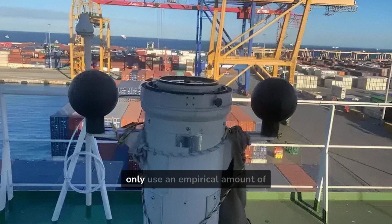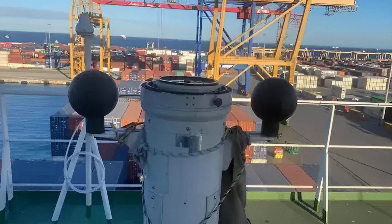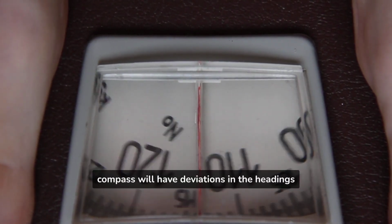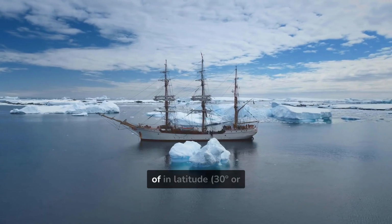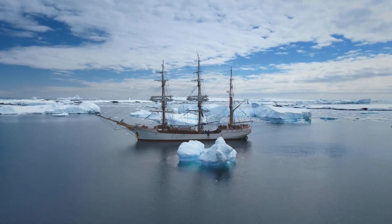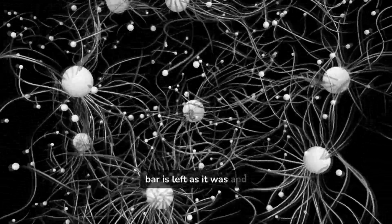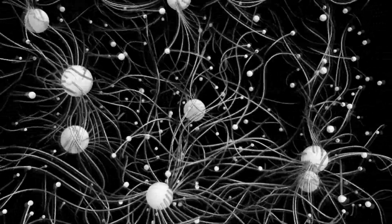The Flinders bar is installed when the vessel was built and the adjuster has nothing to do in this matter. Only use an empirical amount of Flinders bar, 30 centimeters. If the length is not appropriate, the compass will have deviations in the EW headings when the vessel changes a lot in latitude, 30 degrees or more. So, the Flinders bar is left as it was and the sphere also in its position, if the compass has been adjusted previously.